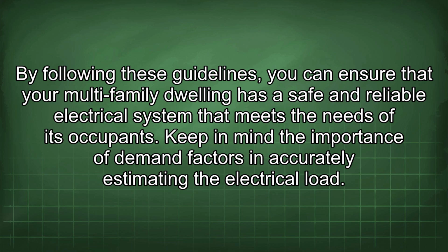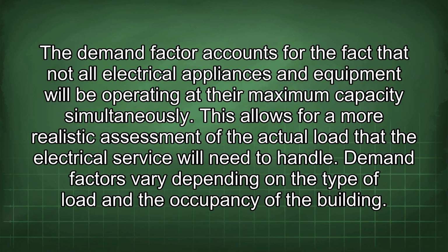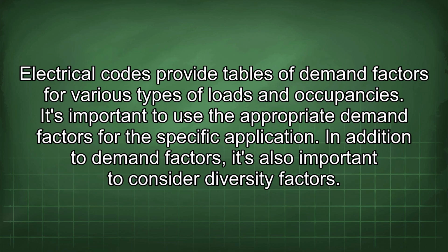Keep in mind the importance of demand factors in accurately estimating the electrical load. The demand factor accounts for the fact that not all electrical appliances and equipment will be operating at their maximum capacity simultaneously. This allows for a more realistic assessment of the actual load that the electrical service will need to handle. Demand factors vary depending on the type of load and the occupancy of the building. Electrical codes provide tables of demand factors for various types of loads and occupancies. It's important to use the appropriate demand factors for this specific application.